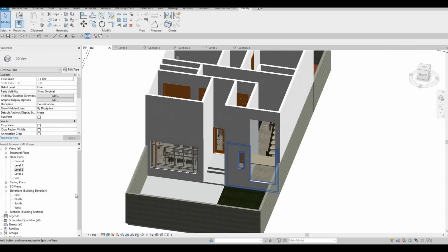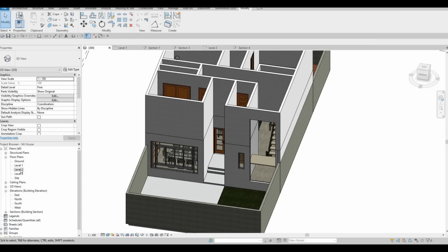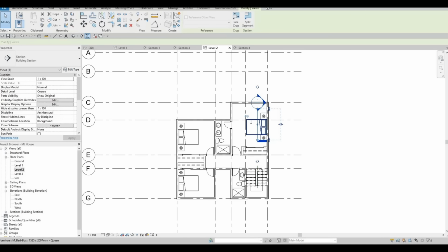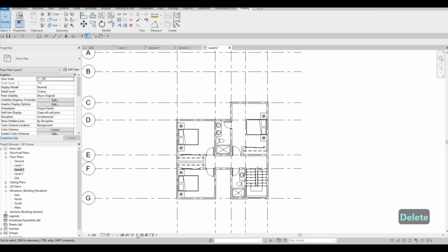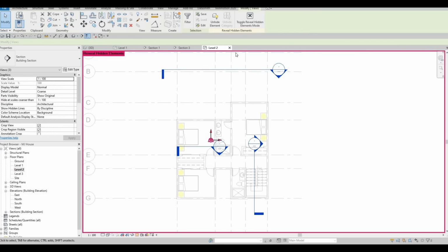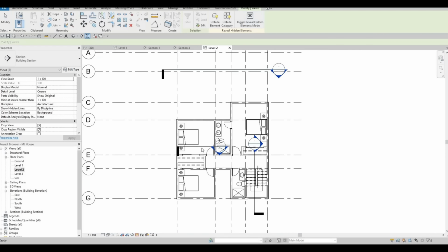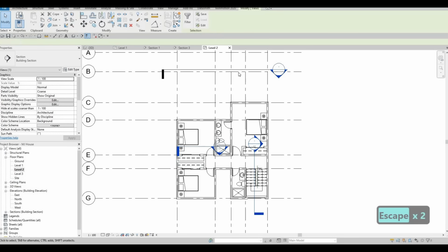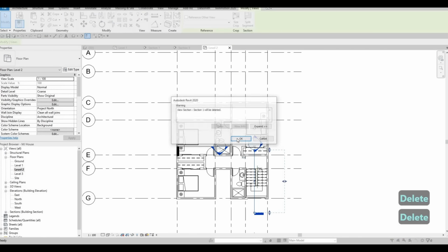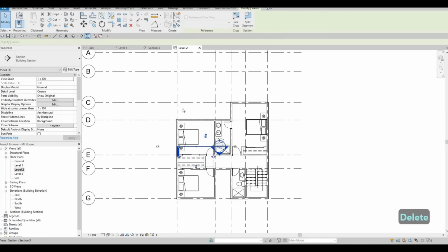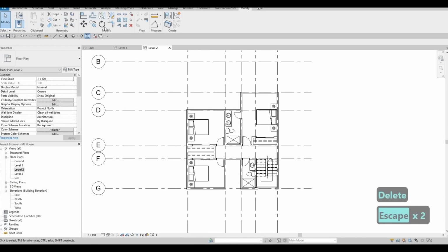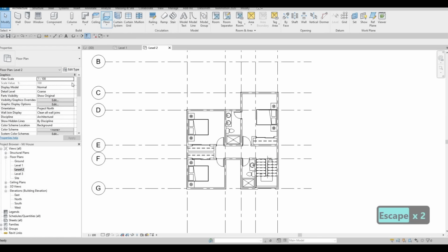And then after that, what we could do is we could place the floor. So here I'm just going to delete this for now. I'm also going to unhide all of this because we don't need it anymore. And I just remember to, I rather delete it than to hide it. And then let's go to architecture, click on floor.